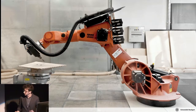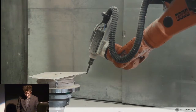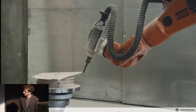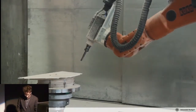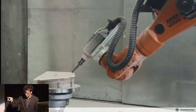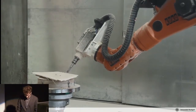In this case, all you need is a 7-axis robotic setup and a spindle, and that will allow you to mill any kind of finger joint in any kind of thickness, in any kind of angle. So, compared to the standard CAM, computer-aided manufacturing software, we developed our own little manufacturing process, telling the robot to mill the boundary of this plate, and then the miter connection, and then the finger joint. So it's like 3 different jobs that it's doing on each edge.